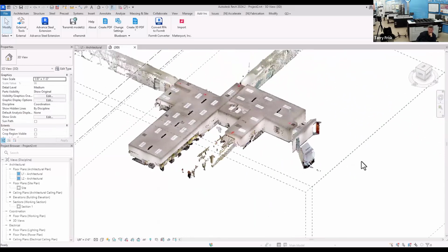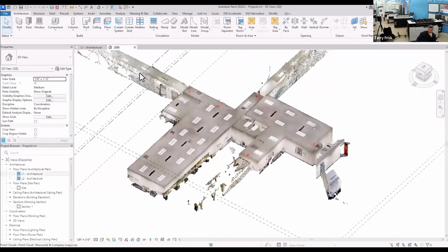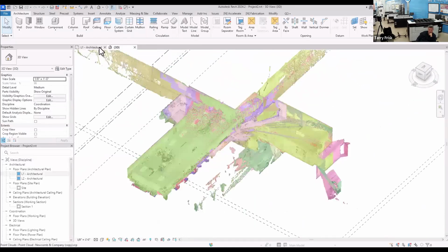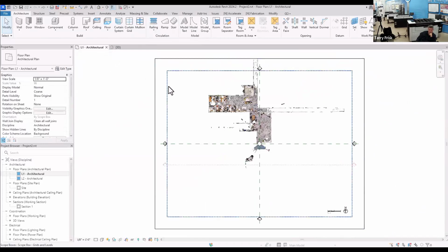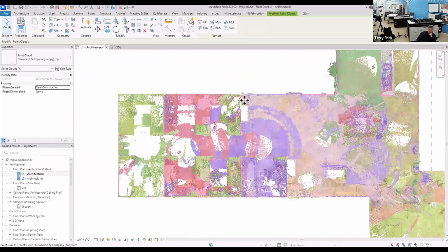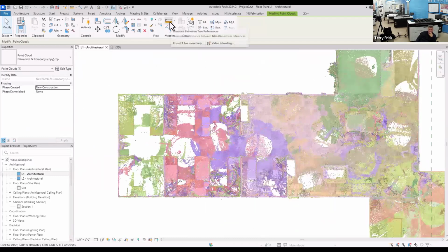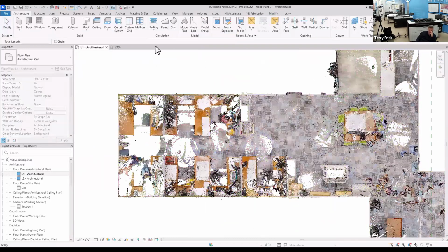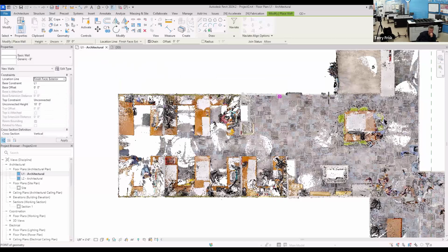Additionally, different color modes can be used to view the point cloud data, like RGB, intensity, elevation, and so on. By eliminating the need to manually measure distances in the field, we now have all of that information at our fingertips within the model. Check for wall lengths, opening sizes, and clearances by simply locking onto the points themselves for accurate values from the scanned information.